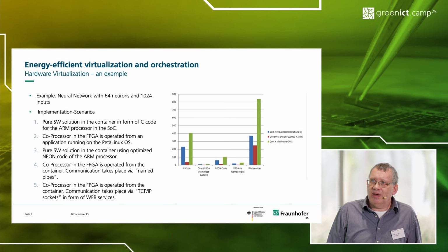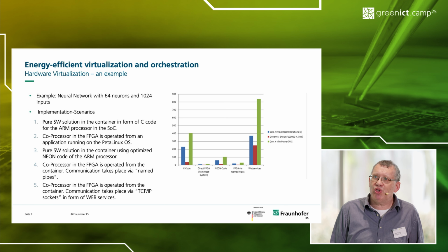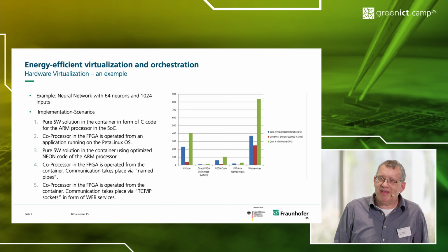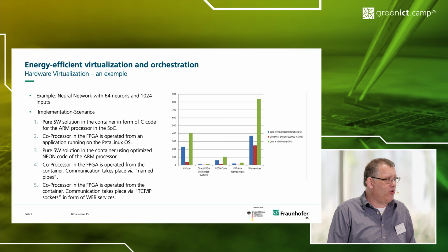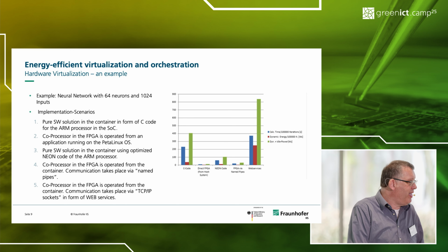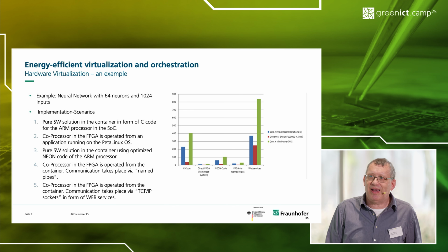And you see in C code, you have a long calculation time, and you also have a big amount of dynamic energy. The next part of the diagram shows the same functionality, but completely realized inside the hardware of the FPGA, and you see the difference. But the problem is, this is only the implementation. We also have in this implementation the need for the interface communication between the software part and the hardware part, and this is not included in this diagram.